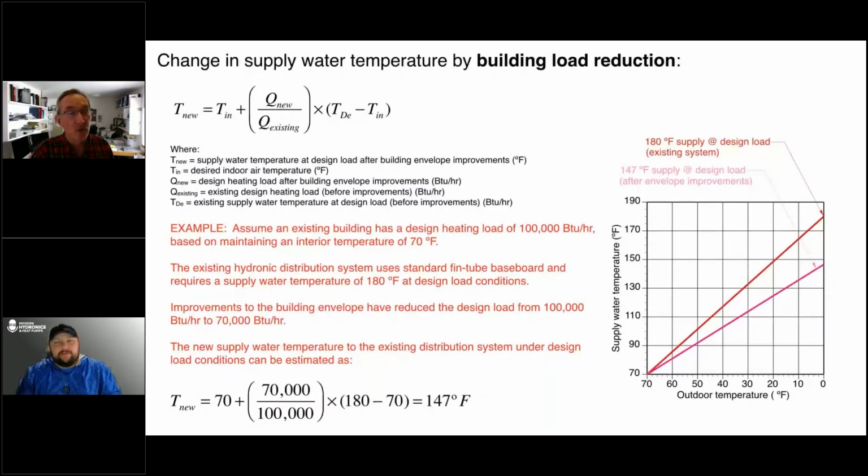It's a great question. It's one I'm assuming a lot of people think about, but you're going into kind of dangerous territory there, as I'm sure you appreciate. The problem you get into with chilled water and fin tube is, as soon as that water temperature gets below the dew point of the room air, you're going to form condensation on the tube and on the fins. And a fin tube baseboard has no way to capture that condensate.